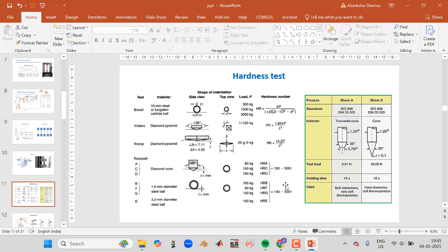But overall hardness is a surface property, and we can also check elastic modulus from that. If I perform a nano indentation test, I can still get a stress versus strain curve, and the hardness value I can get, and elastic modulus also I can get. So from the stress strain curve, I can calculate the yield stress also for polymers. So I can just draw it for you.